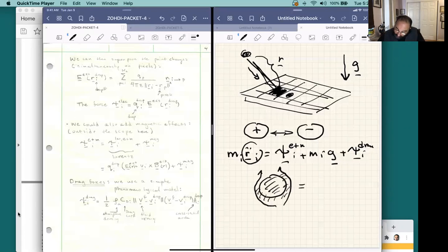So the forces on the surface are really the integral of the stress. We're going to talk about concepts of stress momentarily in the next week or two, integrated around the body of the object, multiplied times the normal, integrated over the area. The normal direction, n, is the outward normal to the surface of the object.